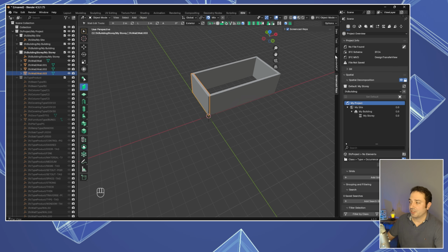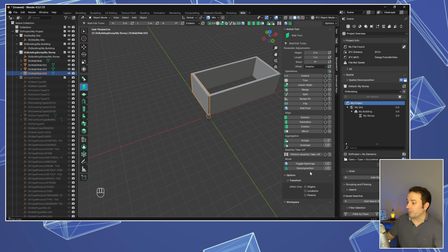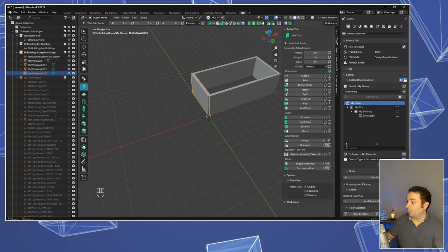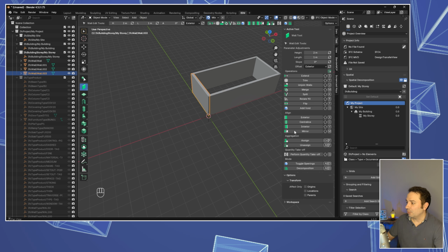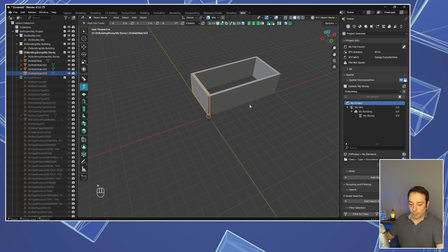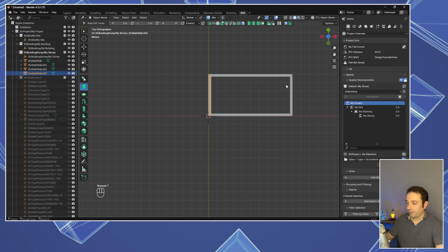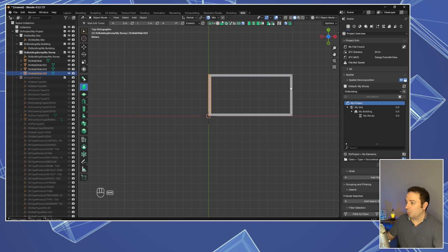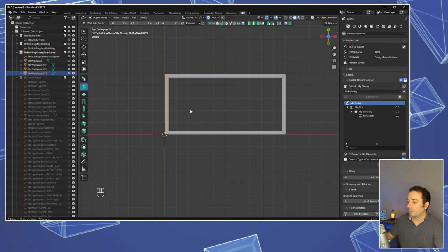I'm going to show you that you have the possibility to have some other Bonsai tabs. If you go to Tools, you can see that there is a lot more that you can start exploring. Please follow the documentation because you might get lost quite easily. To close this tab again, we just press N. So let's go back to the top view of this building and add something more. If we want to move in different parts of the visualization, you press just Shift and the central button of the mouse.